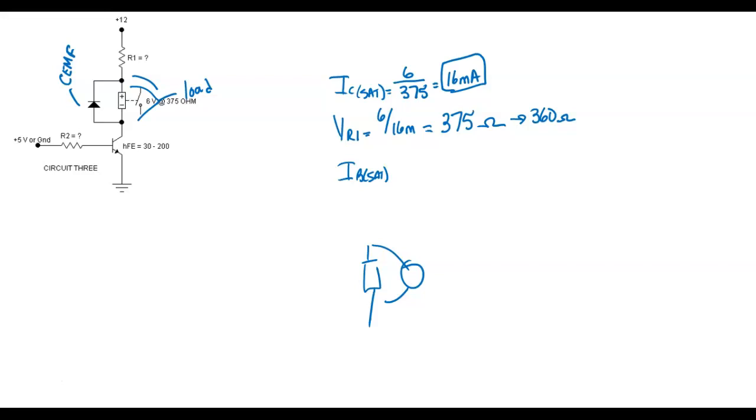Because if you double the voltage, according to Ohm's law, voltage and current are directly proportional, so the current doubles, and power is V times I. So power varies with the square. I would make that coil produce 4 times the power it's supposed to produce. So what would probably happen?